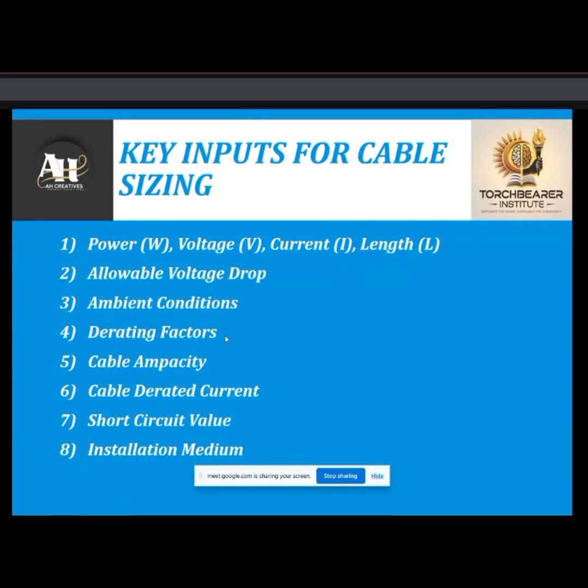And when the current is derated through the derating factor values, we will compare it with our load current. On that basis, we will define our cable size. The cable derated current is basically the ampacity of the cable multiplied by the derating factor. The derating factor comes from the multiplication of the different values given by the manufacturer or the IEC standard.